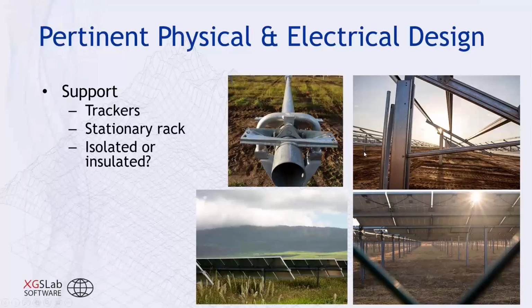And I've not personally worked on one, but I've heard there are some manufacturers that will actually specify insulated and isolated supports so that there's not a bonded connection from the panels to each of these posts. So that would be one area that's going to drive how we model our grounding system, as we'll see when we step into modeling later in this webinar.